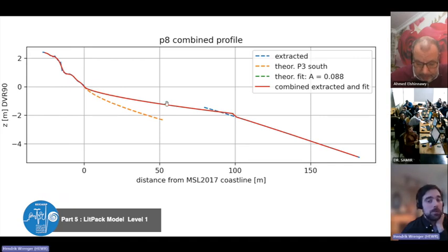Another way of doing it would be to go down to the depth of that offshore and then connect it in a straight line, arguing, yeah, maybe there is that sediment and then it hits a non-erodible layer, and that's why it continues so shallow offshore. That's again things that we don't know and that we can perform sensitivity studies and then make a judgment of in what range the impacts of these simplifications can lie.